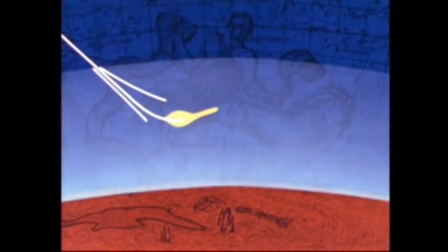The trajectory the command module will follow is basically as follows. It will enter on a given flight path and proceed downward to the pull-up point. Just before pull-up, it enters the atmosphere dense enough to allow aerodynamic control of its landing point and begins its first control period. The command module will then climb until it skips out of this denser atmosphere. The skip is primarily to increase the maximum range of the spacecraft and to reduce the aerodynamic heating load on the heat shield.